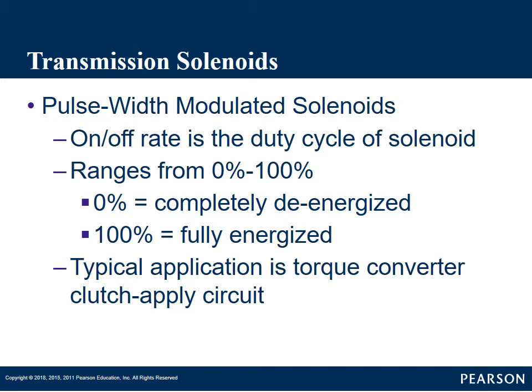In an electronic transmission, they still monitor the load of the vehicle and the speed, but those no longer directly affect the shift valve. All they're doing is telling the computer that it needs to operate fluid pressure in conjunction with the load.